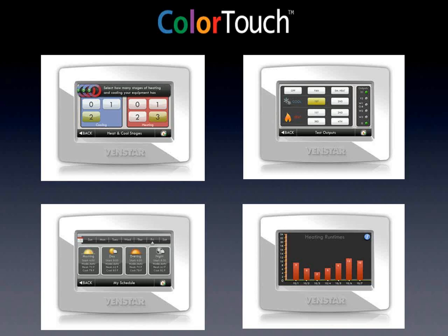There's also a pretty cool checkout mode. Over on the top right-hand side over here, the checkout mode is allowing you to initiate whatever stage of heating or cooling you want to test it out without having to go through the normal settings and all the normal delays and all that kind of stuff.